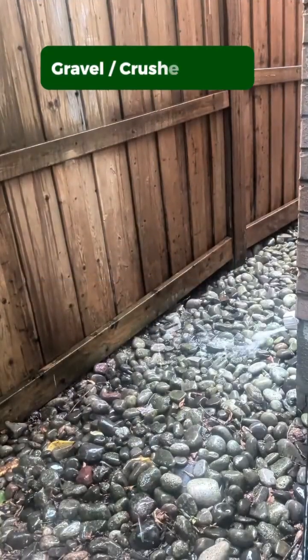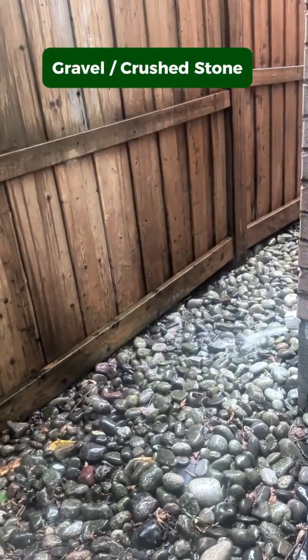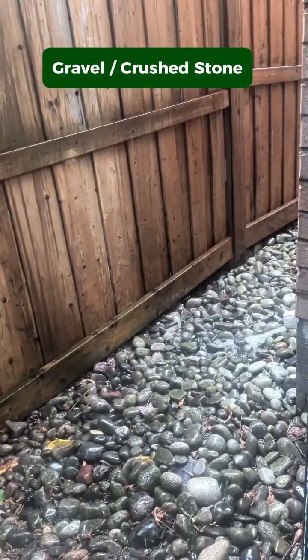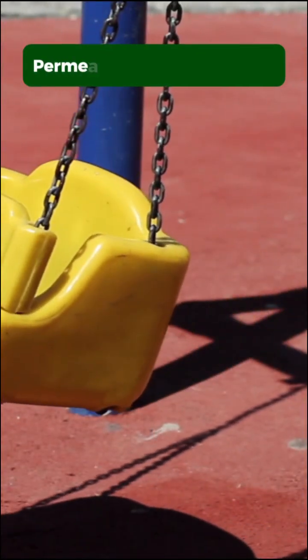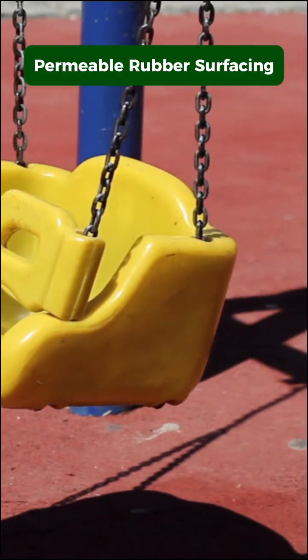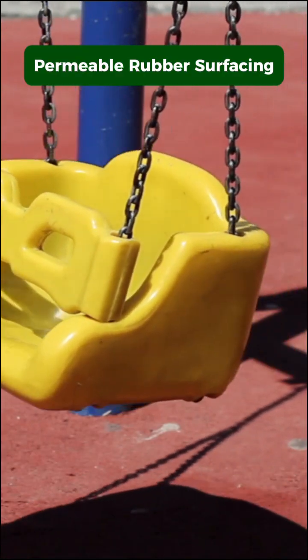For lower traffic areas, gravel or crushed stone offers excellent permeability and is commonly used for pathways, driveways, and stormwater management areas. Playgrounds and recreational spaces can use permeable rubber surfacing. It not only allows water to drain, but also provides cushioning for improved safety.